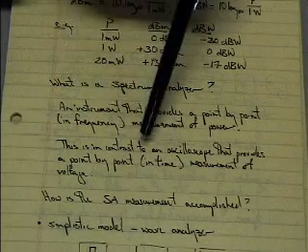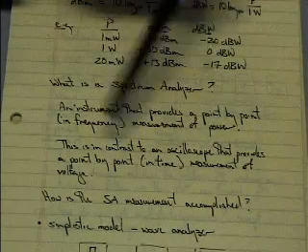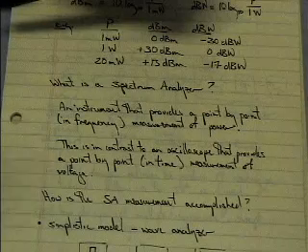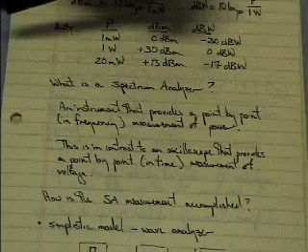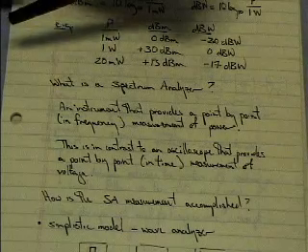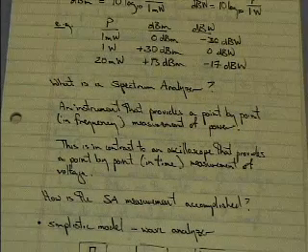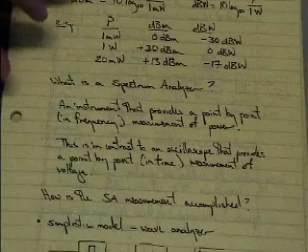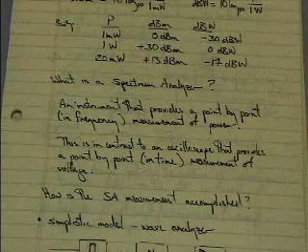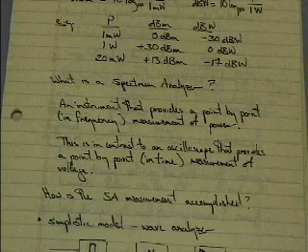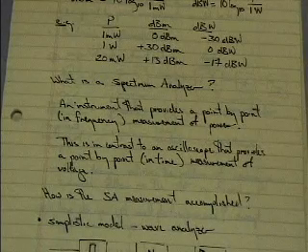Now this is in contrast to what we're perhaps more familiar with, an oscilloscope. We look at an oscilloscope, our x-axis is time, and what we're plotting in the y-axis is voltage. So an oscilloscope does voltage versus time. A spectrum analyzer does power versus frequency. If you go back to Signals 171 or whatever class you may have had, this whole duality of signals lying in the time domain and the frequency domain: oscilloscopes allow us to look at things in the time domain. Spectrum analyzers allow us to look at things in the frequency domain.